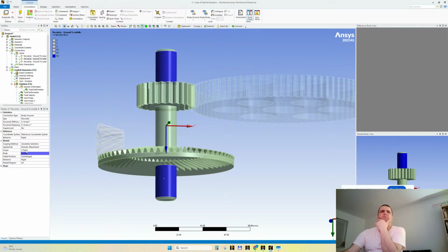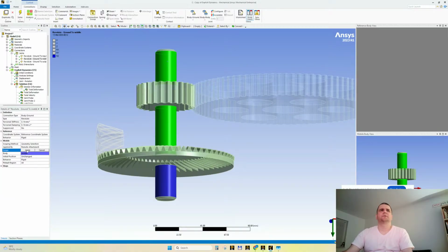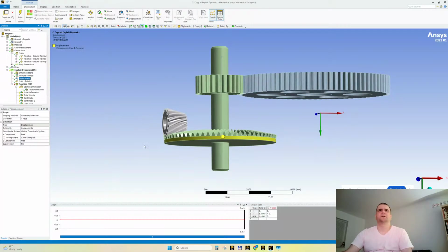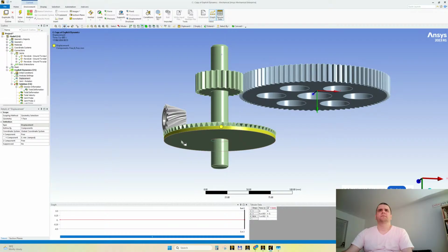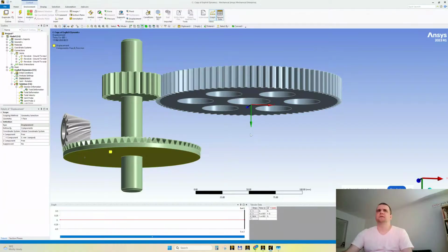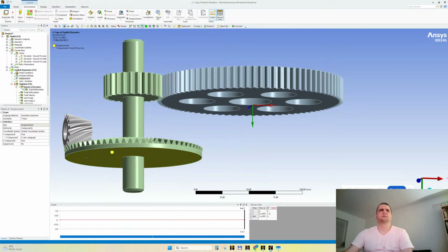Can I dare to make here and here the Revolute joint? Let's see if I dare. Then this would mean maybe I can change this face here and not allow it to move axially regarding the y-axis.